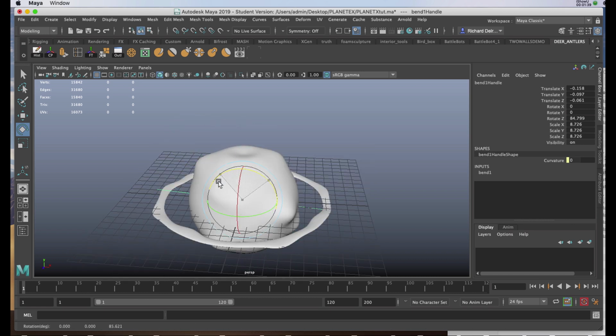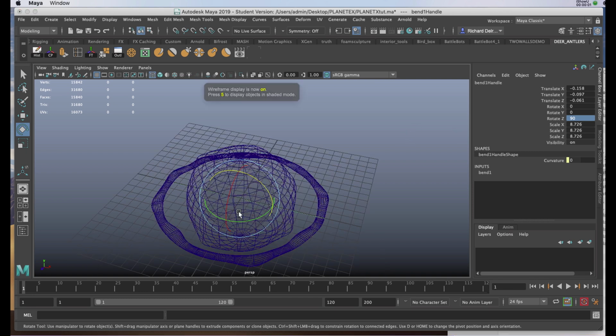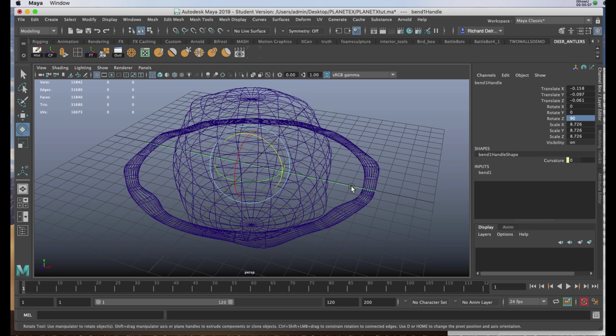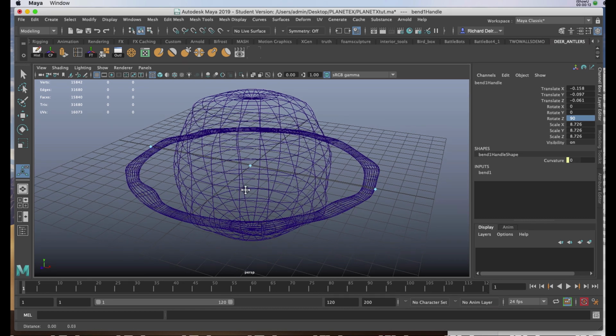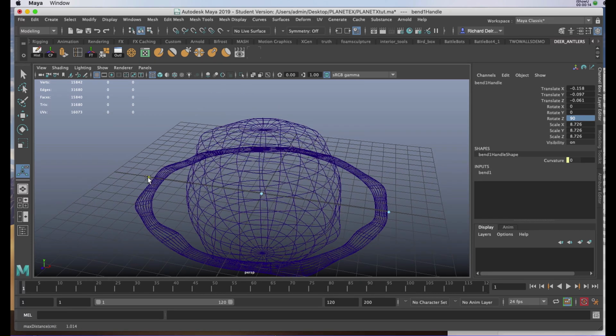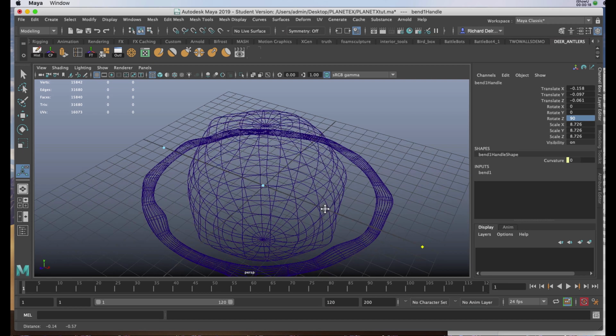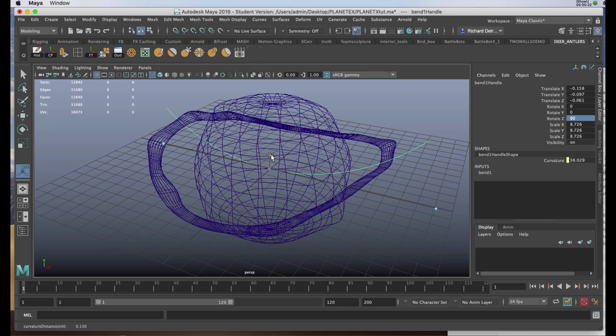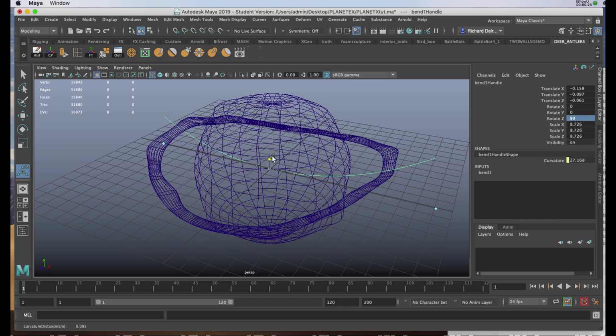Now I can also change it and be more precise if I choose inside the channel box. I'll put in 90 degrees. I'll hit 4 on the keyboard so I can see the green line as it goes through the geometry. Just like our lights, if I hit T on the keyboard, I can transform and sub-edit. 2 blue diamonds appear on either end, which allow us to extend the parameters of the bend, and the one in the center, when we pull down on it, will give us a bend contour.